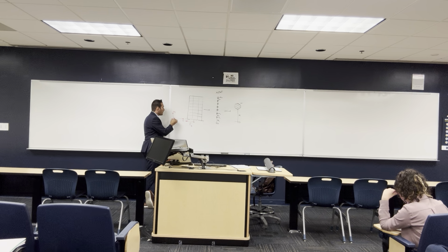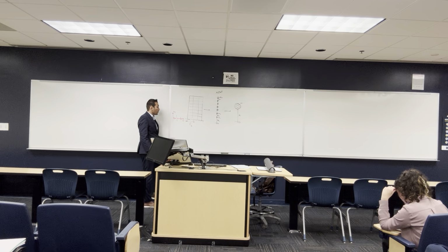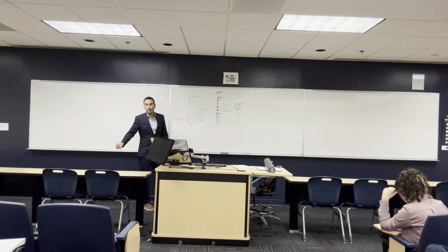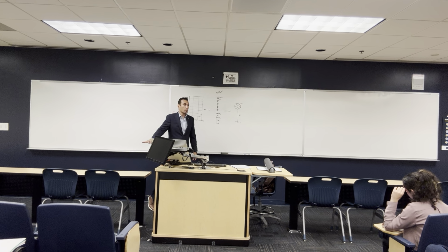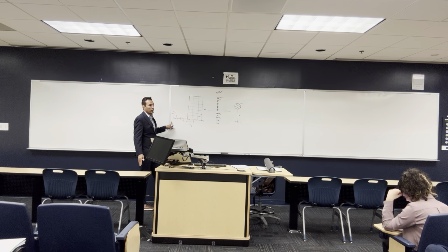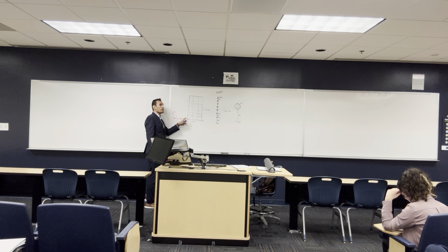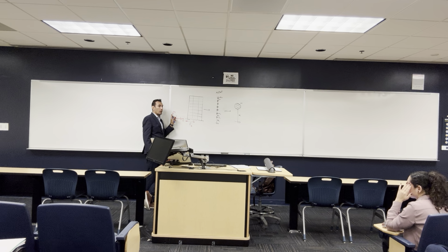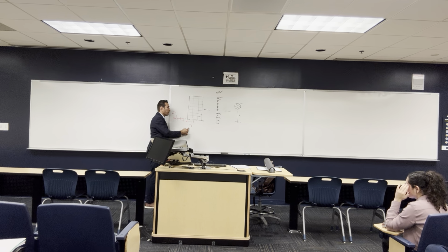This is the time history of the acceleration. So it's like you put devices in the soil and keep measuring how the soil is moving. It's going to give you something like this. If you know the mass of the building and you know the acceleration of the ground, you can know what the F base is. It's the mass multiplied by the acceleration of the earthquake, multiplied with some bunch of factors. So that's what we discussed last time.